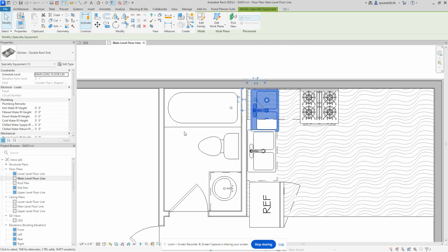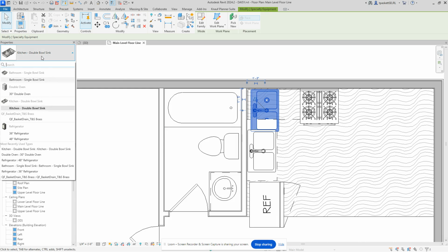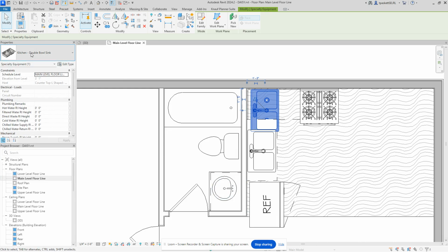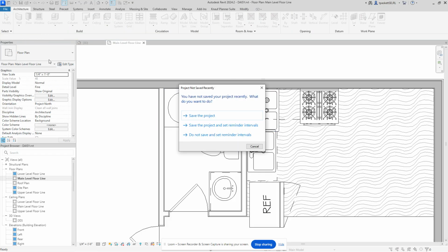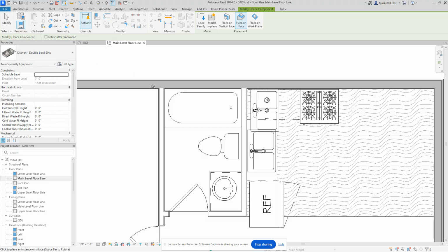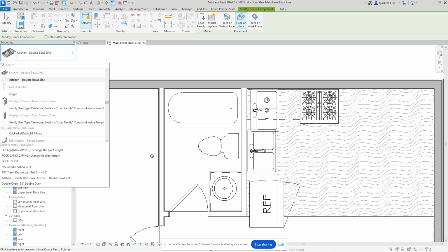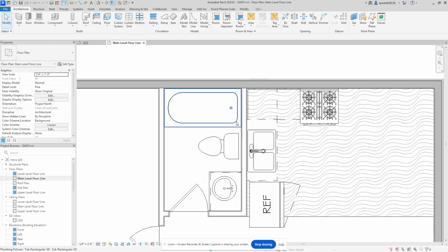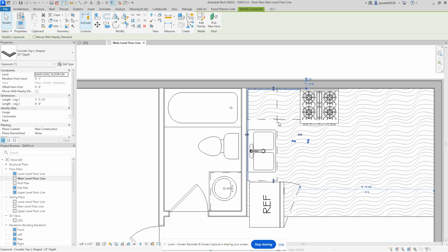So again, we'll do it in 3D again, or 2D. Bring it in, find your countertop, and you can place it there. Yeah, mine goes too. I think it's because my cabinet's not trimmed. My countertop's not trimmed, right? It's not what? I haven't trimmed my countertop. Oh, back and not through the stove. It's through the stove and it's not all the way through the sink cabinet. Okay. So what you have to do is look for these arrows to trim it with.